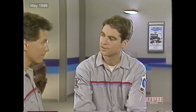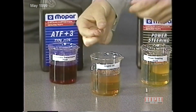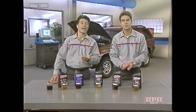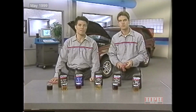Transmission fluid feels thinner. Okay, then try this engine oil. This feels the same. Which leads us to believe in this case the leak is engine oil. Engine oil has a thicker viscosity than automatic transmission fluid. If the fluid had been thicker than the engine oil, then we'd know that it was manual transmission fluid.